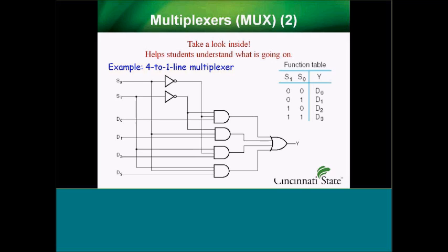You know, and they can always say, oh yes, if they're both 1, the output's 1. And I keep telling them that's true, but the more important way to look at it is if any input is 0, the output's 0. And so that's kind of the thing. So, an example here, S0 and S1 are both 0. Therefore, I've got 1, 1 from the select lines going into the first AND gate, and so that basically means that Y is equal to D0. If D0 is a 0, Y is a 0. If D0 is 1, Y is a 1. And then that's the way it works for every single gate. And I think this helps them understand exactly how it works.